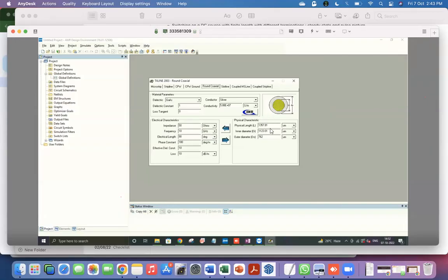As I also mentioned, they are not 100% accurate. You might not get things working at the percent level, but definitely at the 5 to 10% level, matching will be there. For more accurate estimates, you can use finite element simulations as well, which I will introduce today, on how to use it in microwave office.